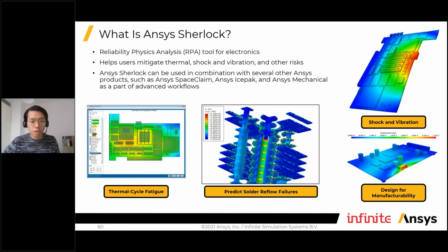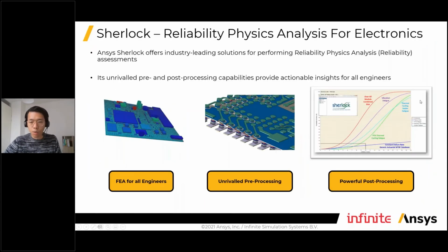Sherlock is a very dedicated tool that is specific for reliability physics analysis. And we're talking about all different reliability issues coming from thermal cycle fatigue, solder reflow failures, the manufacturing and testing process, how much additional temperature you are going to introduce, additional vibration you're going to introduce, and then even the shipping process and the storage conditions, how eventually it will affect the lifetime of your components. As you can see, these are all important factors.